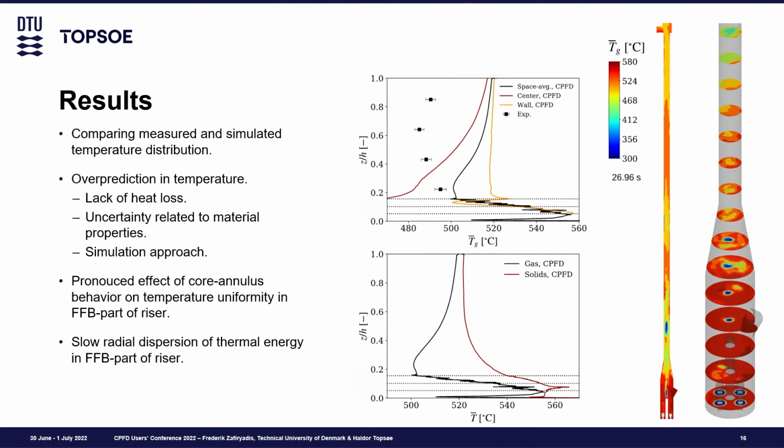And also, if you look at the temperature difference between solids going up through the riser and gas going up through the riser, there's a big gap there. So we're not fully utilizing whatever energy we have in our solids. So we're now working on approaches to improve this distribution by baffles, for example. There's an experimental campaign based on these results coming up here in the fall to improve this.